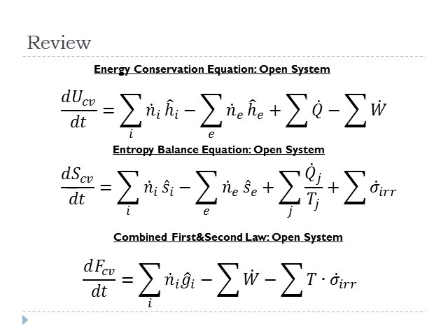And if it's a non-steady-state process, then what you have is the change in the internal energy inside of a control volume, which is your system. The change with respect to time is going to be equal to the flow rate in and out of enthalpy, which as you see, you multiply the flow rate times the molar enthalpy. And because we've used a minus sign in front of the E, which is for exiting, values of N dot sub E are all going to be positive.